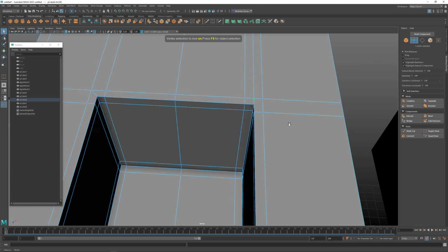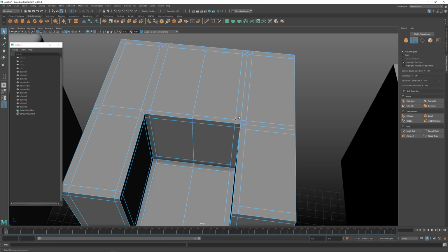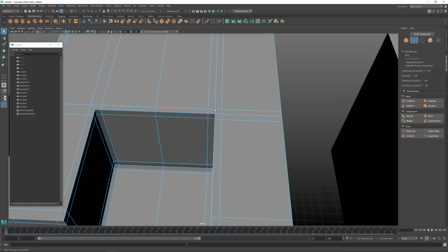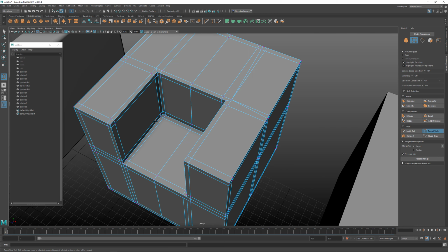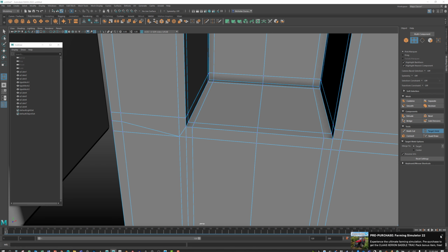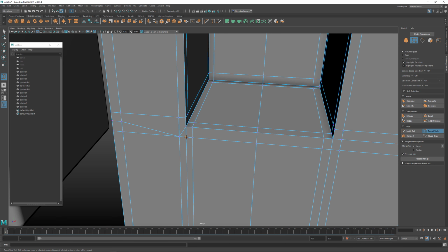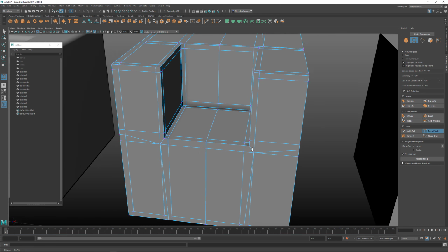So maybe what would have been better is at the very beginning, before I started to delete this stuff out, is to do the same thing in these different areas where I can select this vert, shift right click, say merge vertices, do the target weld, and I can weld this up, and I can weld this up. So I've got this corner handled through here, and now I need to do the same thing for this. Now I got to do the same thing for this and through here. Right here like that. Let's go ahead and push this over and push this over like that.